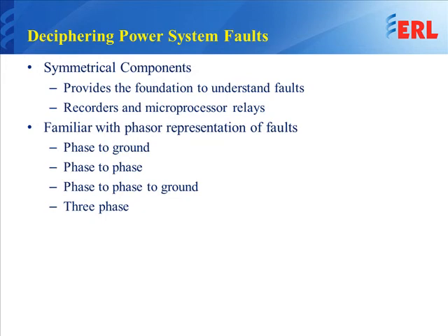Digital fault recorders and microprocessor relays operate and function on the fundamentals of symmetrical components. Also, familiarization with the phase representation of faults is very important because it tells you how the vectors behave during faults, and you can easily picture how these vectors work and respond to power system events, and then you can decipher what kind of fault that would be.